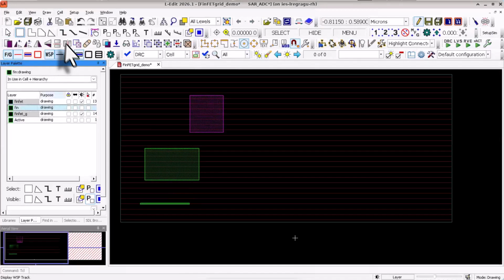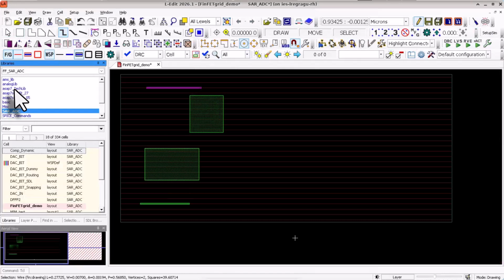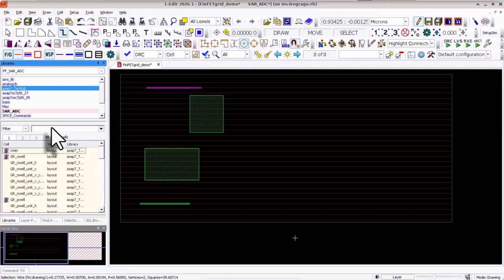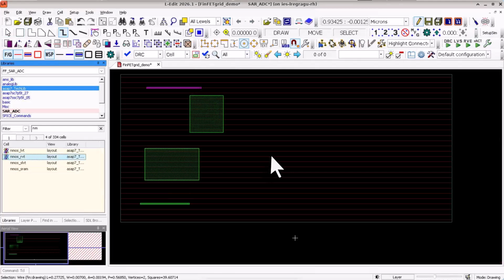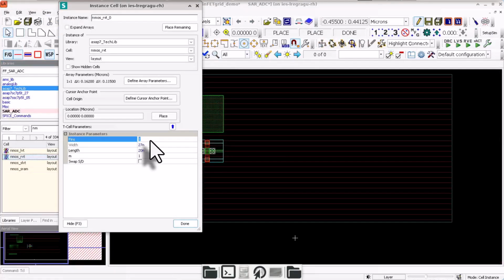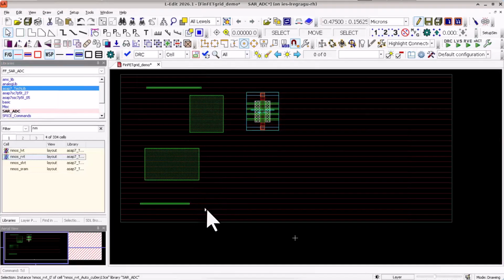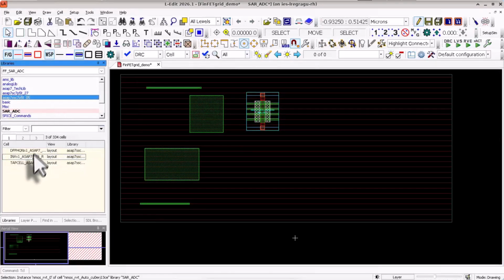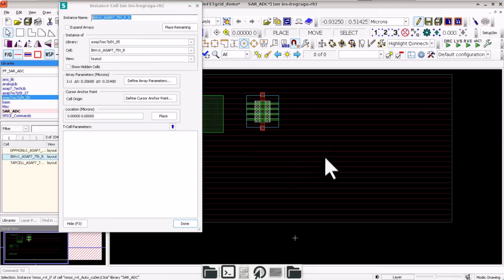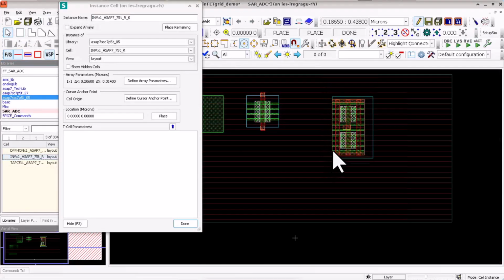The key benefit is snapping. With the FinFET Grid enabled, shapes automatically snap to valid grid locations. This behavior is not limited simply to shapes. Instances and standard cells also snap correctly, ensuring they align perfectly with the process constraints. Even hierarchical blocks can be snapped consistently, making it easier to maintain rule compliance across all levels of the design.